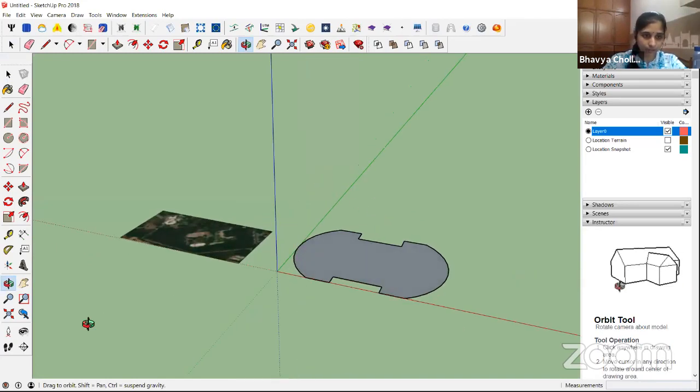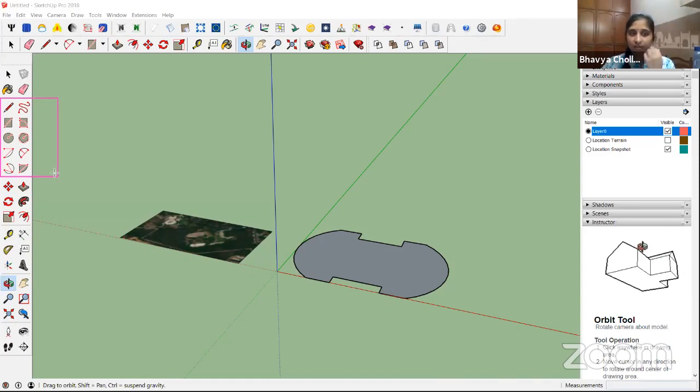Okay. Now coming to this, I'll just select an option called push pull to model. So far we have used the normal drawing tools, like pencil, freehand, rectangle, arc, semicircle, all those things have been used to work with your consideration, right? Now I'm into the next set, the 3D modeling of the complete 2D drawing. Now it's 2D, so I'll make it into 3D now.